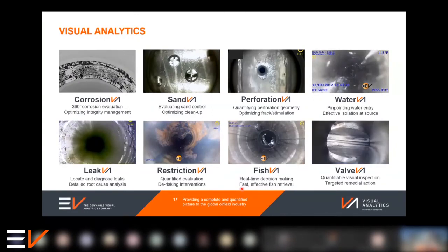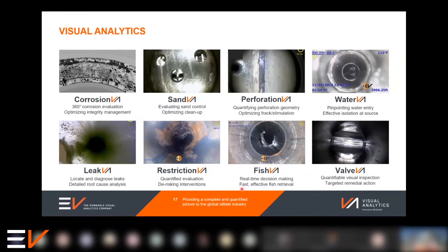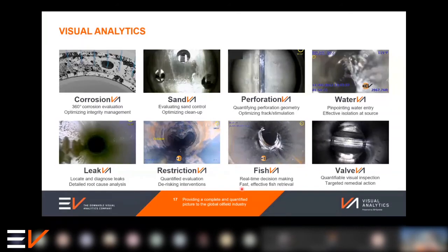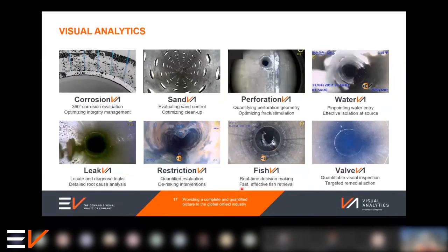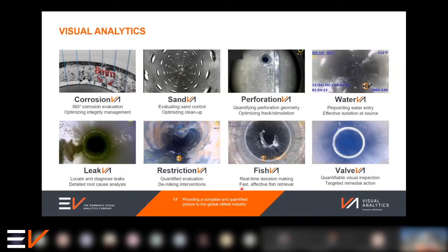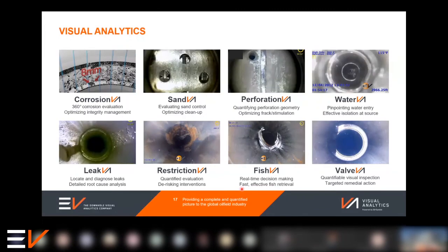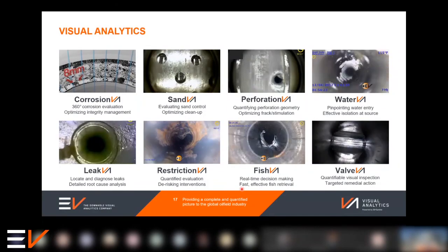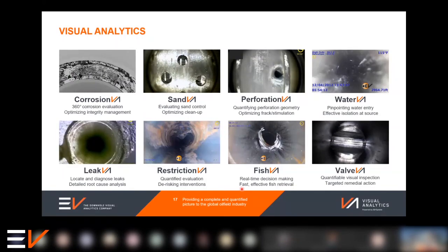And this in itself has led to a fairly rapid expansion of the types of applications that we can use it for. We've shown today some corrosion studies, but we're also using this for investigating sand control problems, looking at screens, potential sites of sand breakthrough and erosion. We look at perforations, their condition, whether they've become plugged up over time with deposits, or even if the original charges have performed to the desired status. We can also use that to help optimize hydraulic fracturing as well.